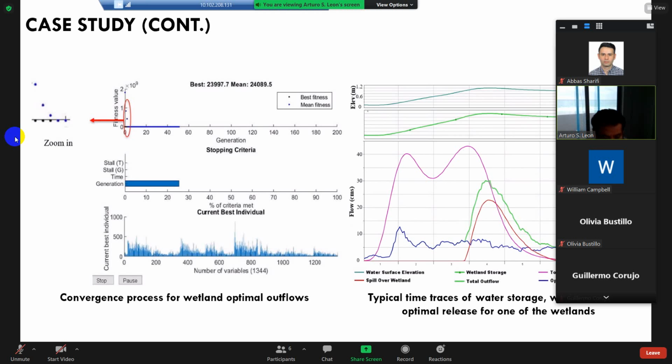So you run the model, you get the results, and then open HEC-HMS and HEC-RAS automatically, but you open in the background. You don't open the actual model. You simply open the files, the text files, in the background and run also in the background, because you are running simultaneously multiple times. I haven't done it for EPA SWMM, but I believe people have done it for EPA SWMM. I'm not sure.